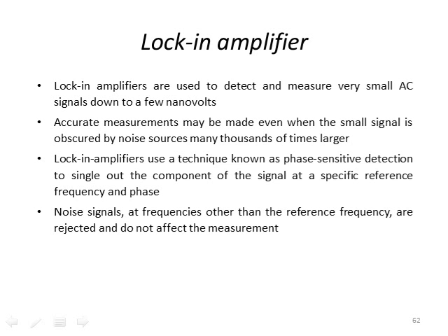So this is what this is saying essentially, is that we modulate to a higher carrier frequency, and then we make a very, very precise filter to filter out only the signal in that modulated frequency range within a bandwidth that's less than 1 hertz. And that way, we can get around large noise amplitudes.